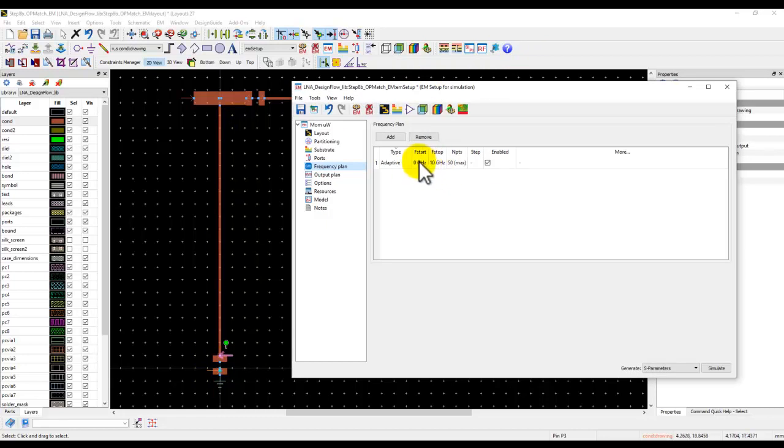If you just run the EM simulation from, let's say, 2 to 3 gigahertz and use that in your amplifier design, and in a schematic you connect a DC power supply here, this layout won't allow the DC to pass because it doesn't have that result in your EM model, right? So always start your frequency sweep from 0 gigahertz to take care of this DC going to this transistor. Very, very important tip to remember.